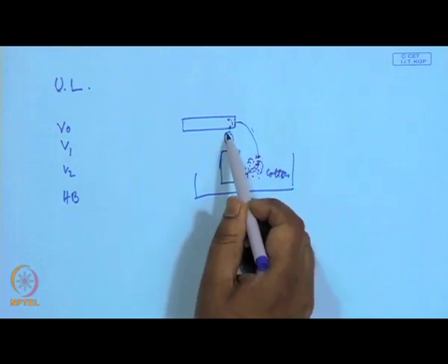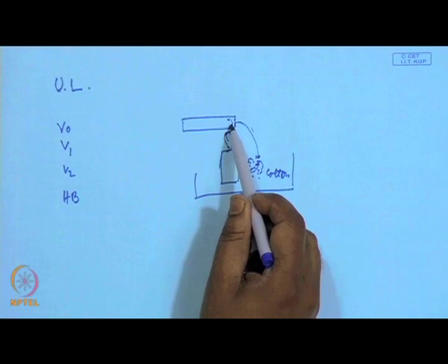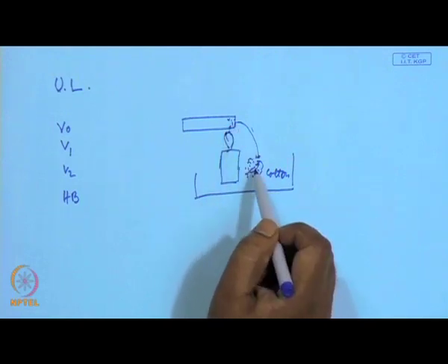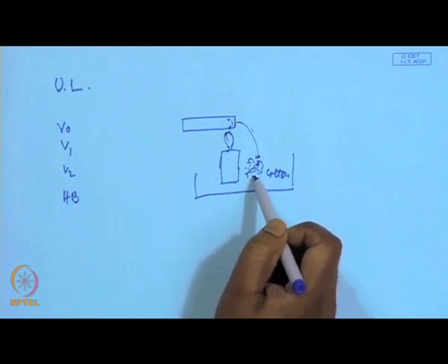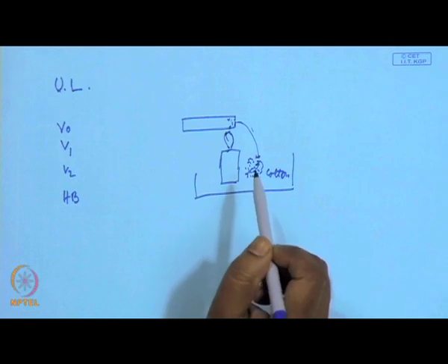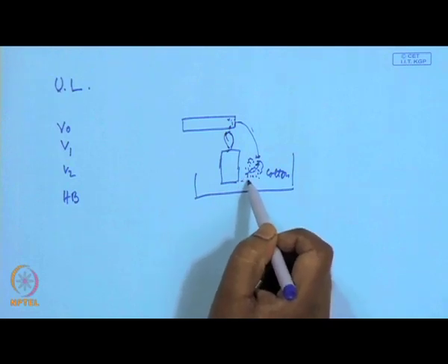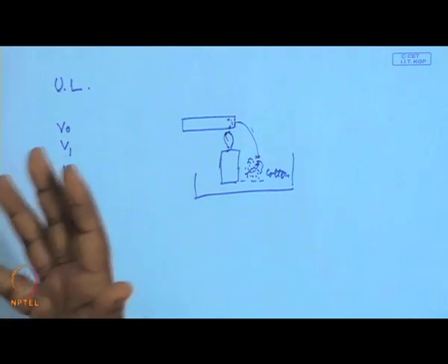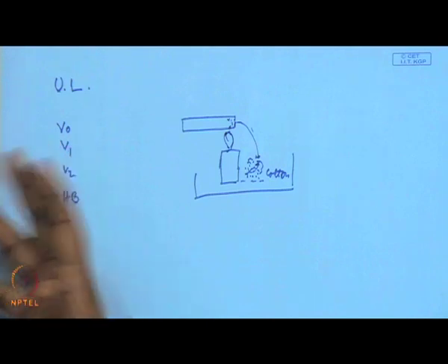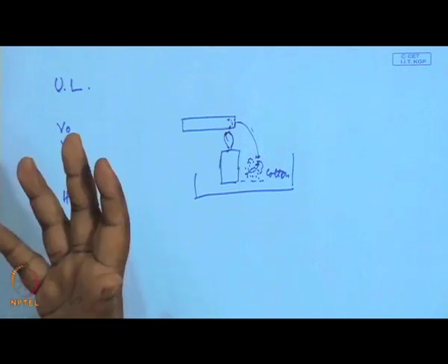So, a sample which burns for less time and which also does not ignite the inflammable material, like cotton, present in the bottom of the container, actually gives the best ranking. It basically tries to mimic the actual application in which the polymers are used.